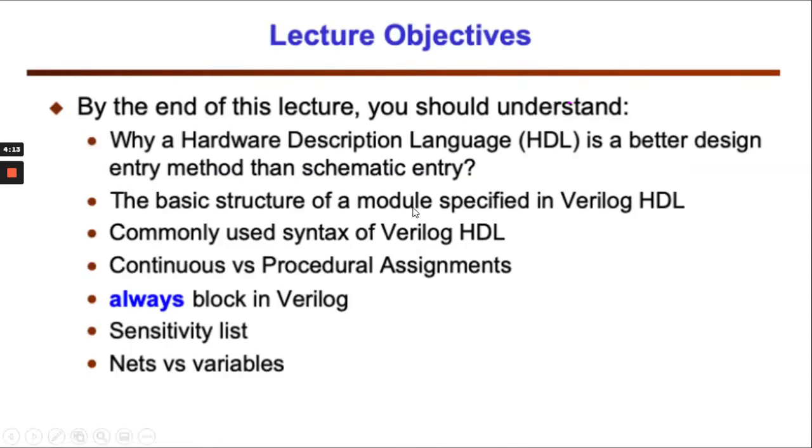Right, so today's lecture objective is that you guys will understand the hardware description language. It's a better design entry method than schematic entry. This is something that we're going to prove throughout this lecture. We're going to compare how HDL helps the designer make their design job easier. And then we're going to discuss the basic structure of a module specified in Verilog HDL.